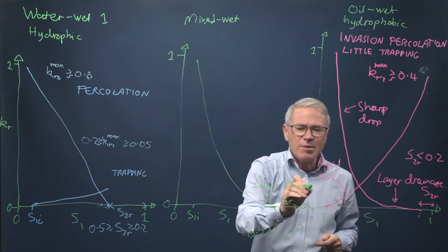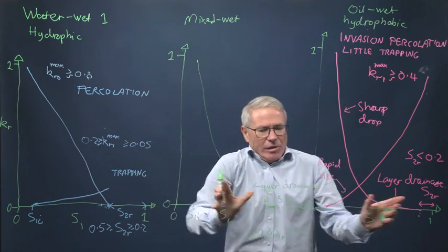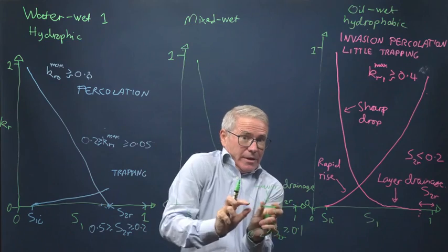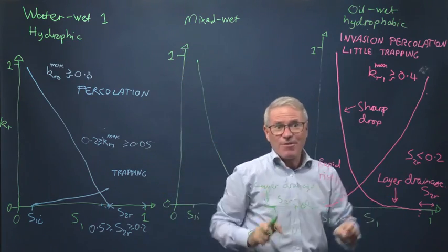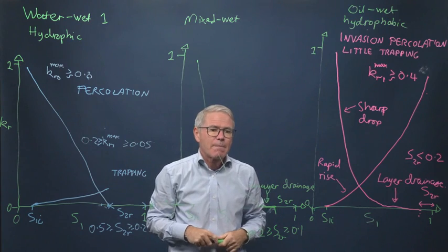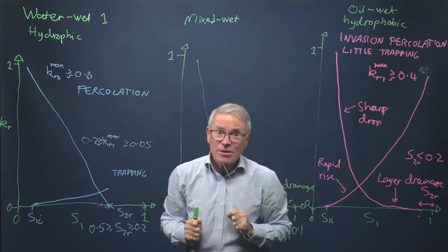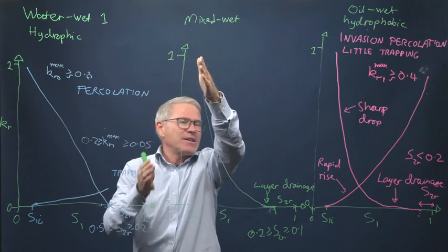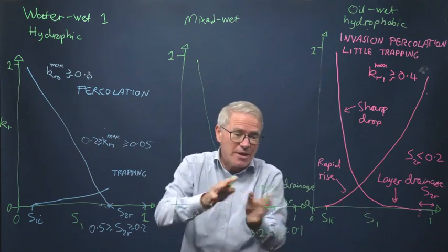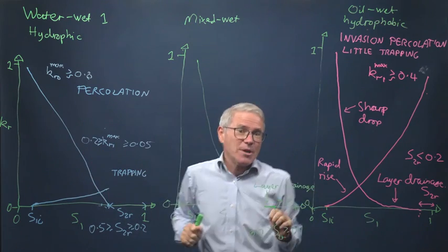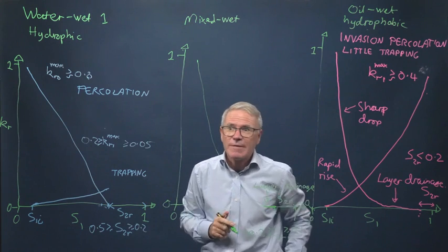So if you look at the relative permeability of phase 2, okay, there's slightly more trapping, there's slightly less of this. It's really very difficult just to judge from the functions what the wettability is. Turns out, so this is intermediate, okay? The amount of trapping is intermediate. It doesn't necessarily decrease so rapidly here as here because now it's filling some water wet regions to begin with, you know. So it's somewhere in between in terms of the relative permeability at phase 2. Fair enough, nothing controversial there.